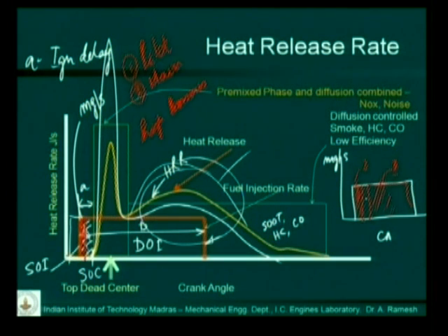So if you increase the pressure to something like, let us say, 1000 bar, we are looking at a jump in pressure. The earlier diesel engines were working at pressures of something like 400 bar, 500 bar. The injector opening pressure is 200 bar, injection pressure could be some 500 bar. But now the trend is to go to 1000, 1600. People are looking at beyond 2000, some people are looking at 3000. 3000 bar is an unimaginable pressure, if you can really see. 3000 bar, if you convert to meters of water, you just try to convert and see, it is 30 kilometers of water.